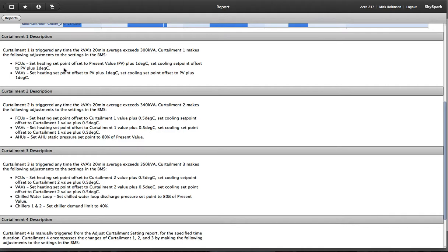They're looking at a display that says 22 degrees, but in reality, with this offset, we're actually moving towards a set point target of 23. So it keeps the occupants happy because they're seeing that visual. As long as they're not feeling uncomfortable, there's no reason for them to make complaints to the building manager.